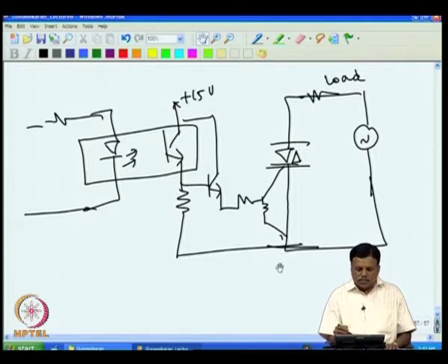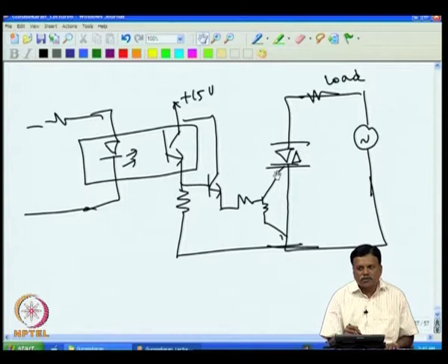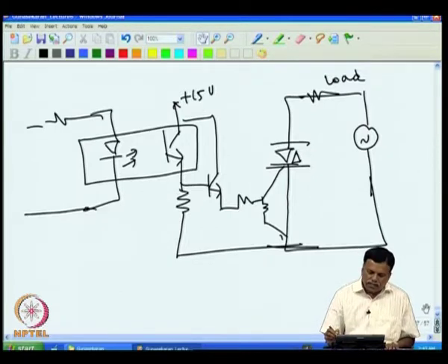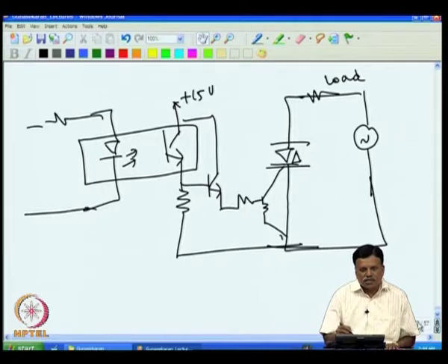Now the circuit can be further improved in the sense that we can make the triac fire only at zero crossing. That is also possible. That we will discuss probably in the other part, when we are using a drive for a proportional controller. So for the on off controller, these are the different possibilities of driving the heater voltage. This is mainly to practice the formation of different circuits, because one has to acquire circuit design skill only in smaller steps by seeing how each step is followed.